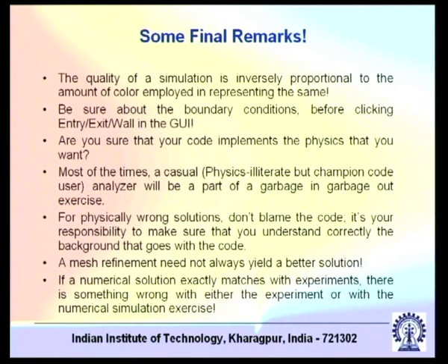Then there are certain issues about meshing. Theoretically we always learn that a mesh refinement will always give a better solution, but practically a mesh refinement to an unlimited extent may not always yield a better solution. The reason is that when you go for mesh refinement, you are sometimes dealing with small numbers, because the grid sizes are small, and those small numbers can interfere with some of the calculations, such as round-off errors and so on. So a mesh refinement need not always yield a better solution. In theory yes, in practice maybe, may not be.